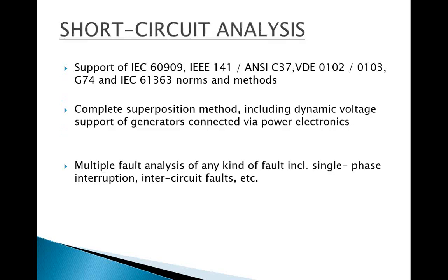In short circuit analysis, we have all the global and standard norms on which short circuit is calculated. We support IEC standards, IEEE standards, VDE, G74 and IEC 61363 norms. So these are different methods and norms on which short circuit analysis is done globally. These are all present in our software.